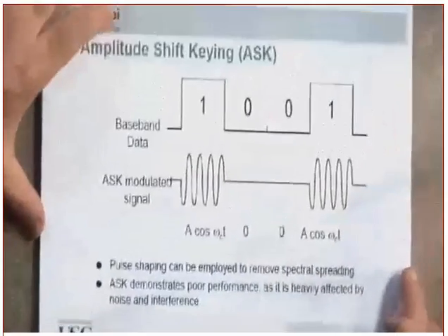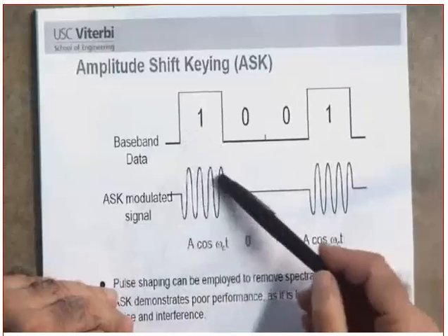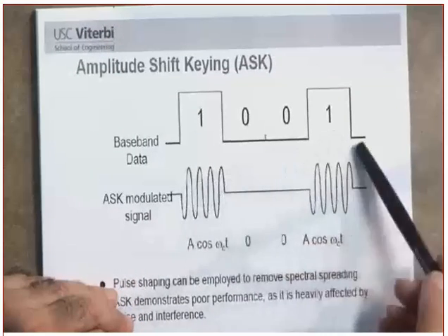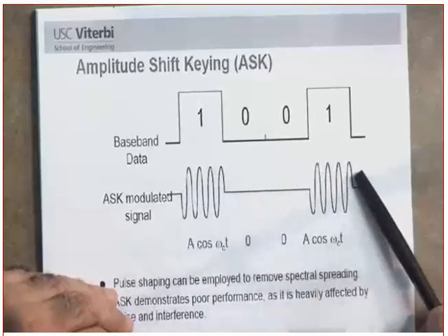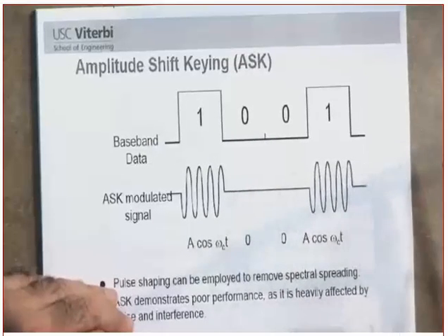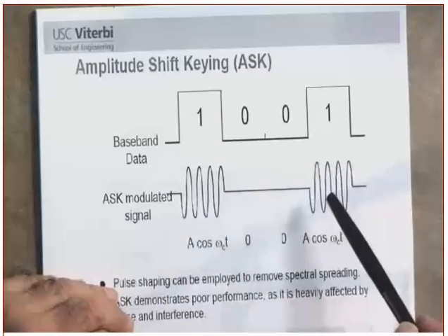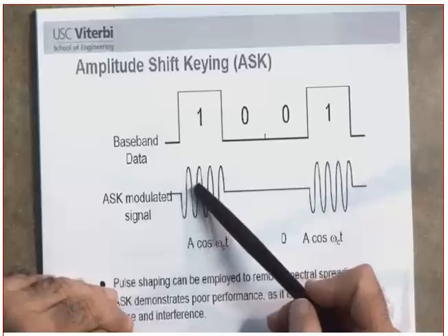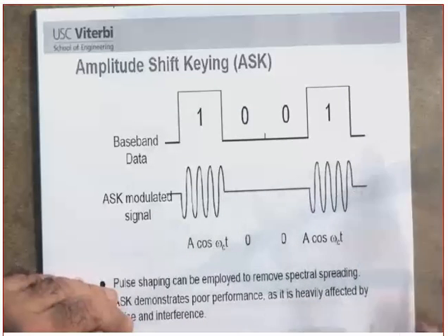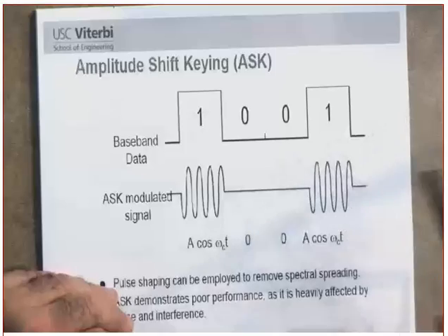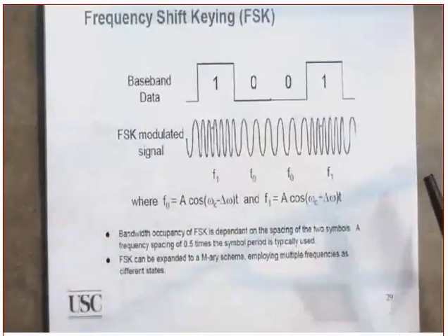Now, let's move on and study a little bit of different modulation techniques. This is ASK, amplitude shift keying, and you can see that the amplitude is changing, whereas the frequency and the phase are not affected. This is ASK. It is rarely used, as I told you before, because the information is modulated onto the amplitude. Every time the information is modulated in the amplitude, you are going to suffer from attenuation and losses in the amplitude.